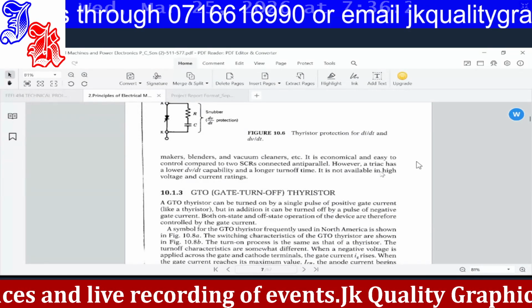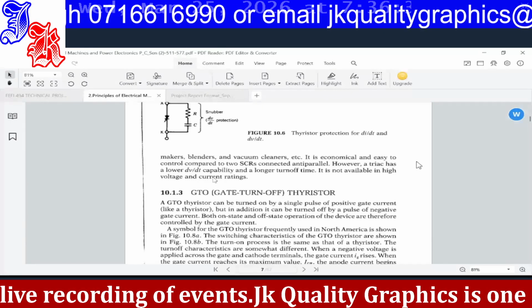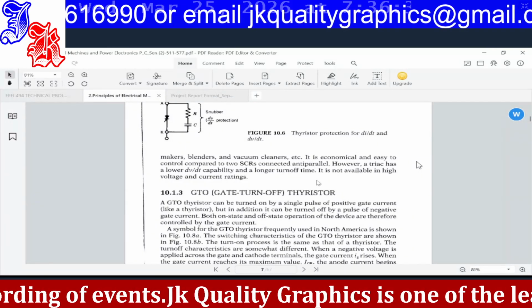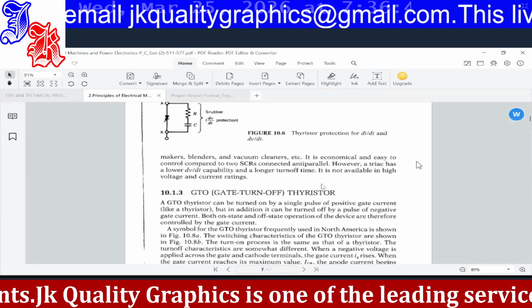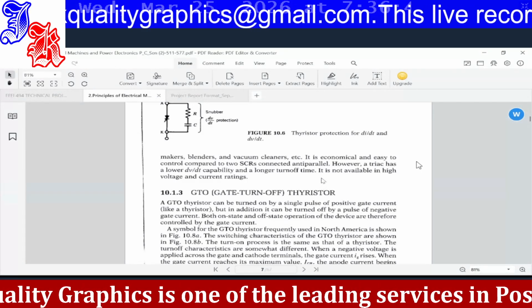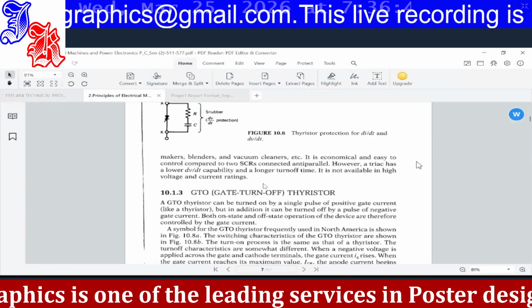However, a triac has a lower dv/dt capability, that is, change in voltage over change in time, and a longer turn-off time. So that is the disadvantage when you compare with just connecting two thyristors. Also, it is not available in high power rating applications.